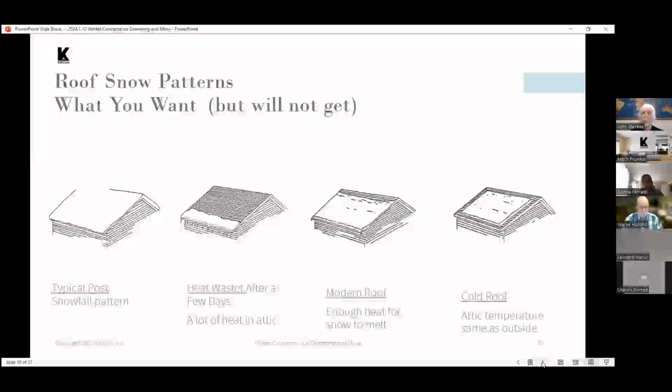And once there's no more snow melt to run down the roof, what you'll end up with at the bottom there is a completely frozen area. There's an ice dam, but there's no liquid water continuing to feed it. And so the leaking that occurs, it really doesn't happen. Everything is frozen.